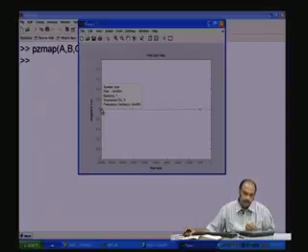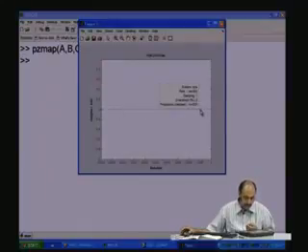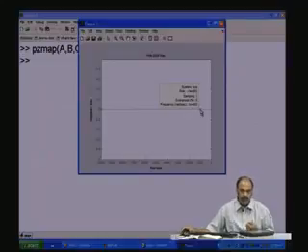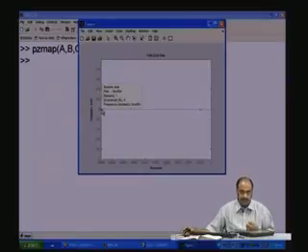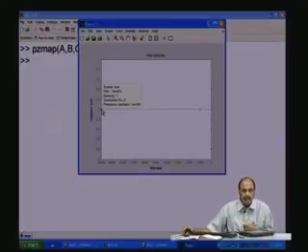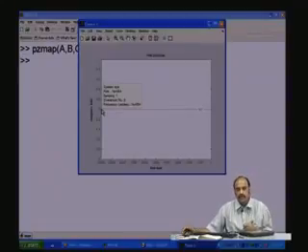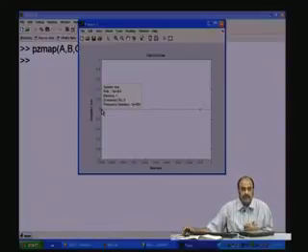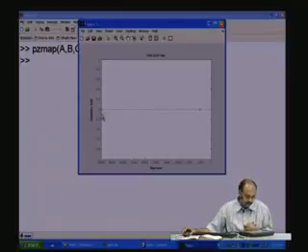So, this system, which has the frequency in radians per second as 10,000, as compared to this system which has a frequency in radians per second as 1000, will definitely be 10 times faster. That is what we saw in the time response, where with the 100 microfarads you saw the rise time of 2.5, and in the case of the changed parameter where C1 was changed to 10 microfarads, you saw that the rise time was 0.25 milliseconds. So, there is the correlation.